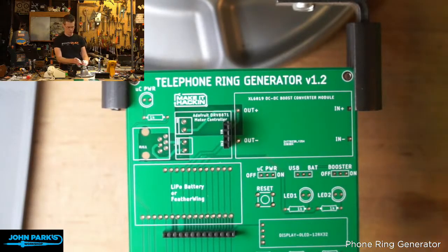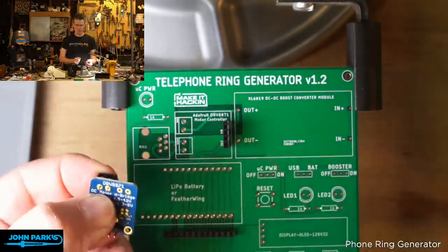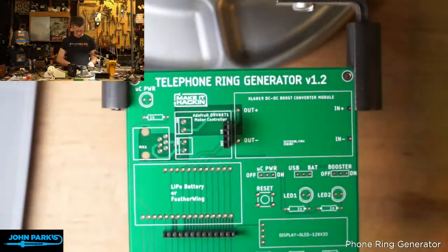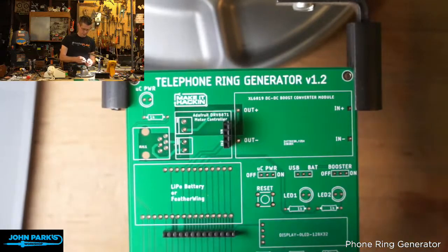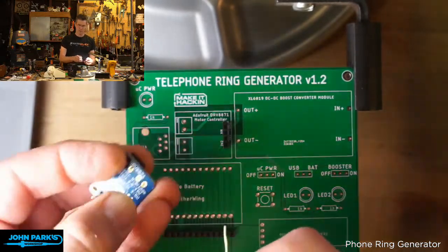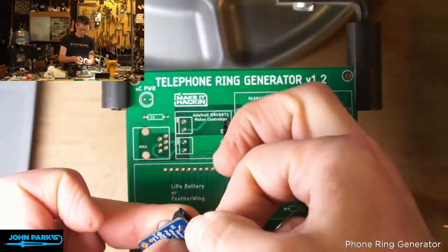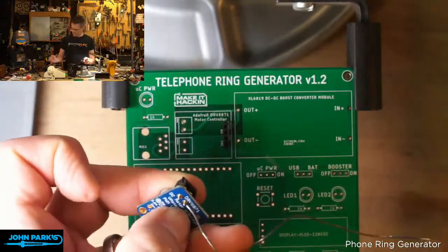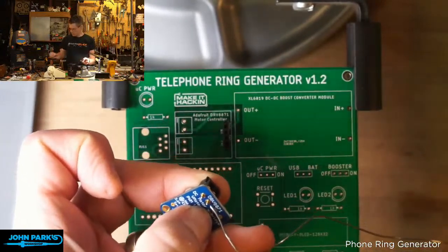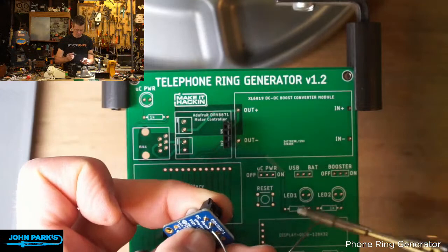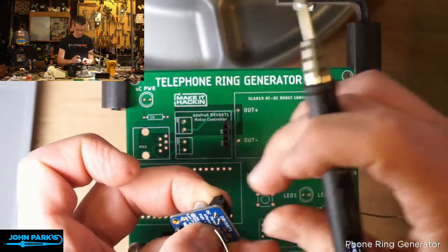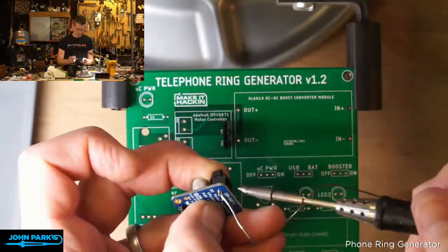So I'm going to do something a lot of us probably do, which is just holding it with one finger, using your pinkies to hold the solder. So I'm going to hold it like this. Bend that down there. Try not to burn myself. This is a totally legit method, I promise. You do want to be careful you're not touching the top of that terminal block, because that will get hot.